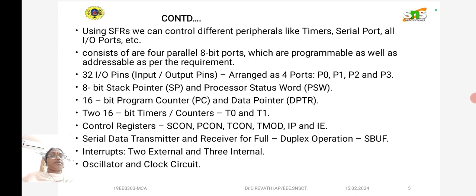It has an 8-bit stack pointer, that is SP, and the processor status word, PSW. It has a 16-bit program counter and also a data pointer, simply called DPTR. There are two 16-bit timers and counters, T0 and T1, and the control registers SCON, TCON, PCON, TMOD, IP, and IE.